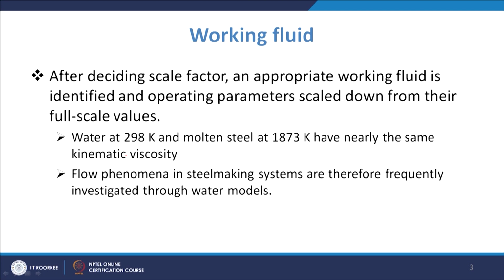It has been found that water at 298 K, about 25 degrees Celsius, that is your normal room temperature, and molten steel at 1873 Kelvin have nearly similar kinematic viscosity, that is mu by rho, and that helps ensure that you have the similar flow regime established in both the model as well as in the actual